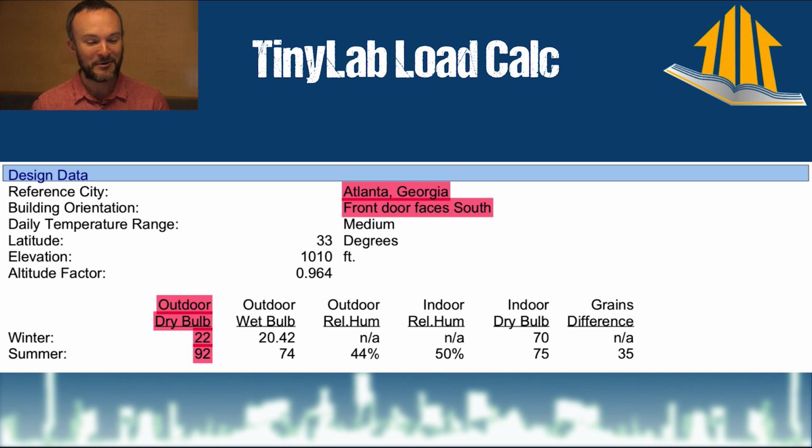Isn't that an interesting experiment? Likewise, in the summertime, if you have a day that exceeds 92 degrees, if it suddenly becomes 96 degrees here in Georgia, I would expect my air conditioner to run nonstop for 24 hours straight. And if it only runs for 30 minutes out of every hour, it means it's oversized. So that's what that's for.